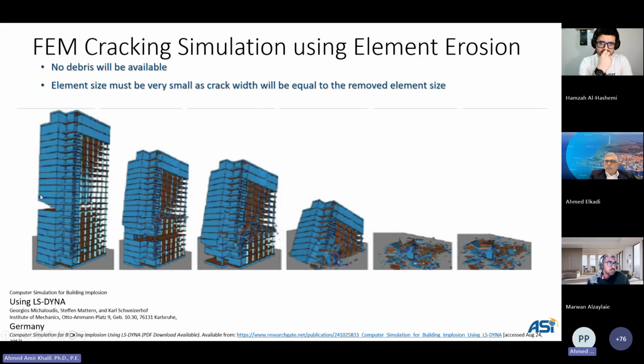So if you study the collapse of the structure like that, for example, using LS-DYNA software, using element erosion, during collapse, you are removing elements. So basically, the structure is melting like an ice cube. It's disappearing as it's collapsing. So those are the techniques that are out there for modeling of separation and collapse at this type of extreme loading.